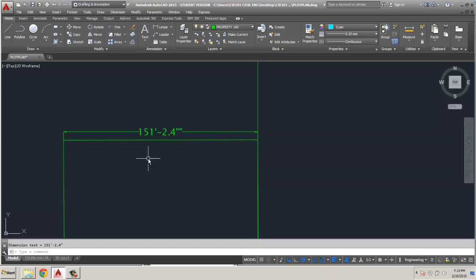Now, if you look on the page I highlighted, I just can't remember where. There it is. Every course will need both linear and angular dimensions. The linear dimension will be the length of the course, and the angular dimension will be the azimuth.